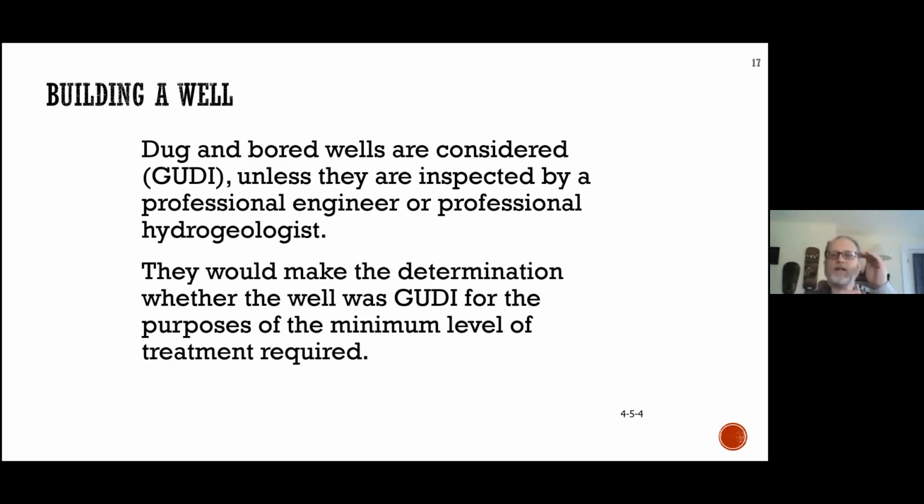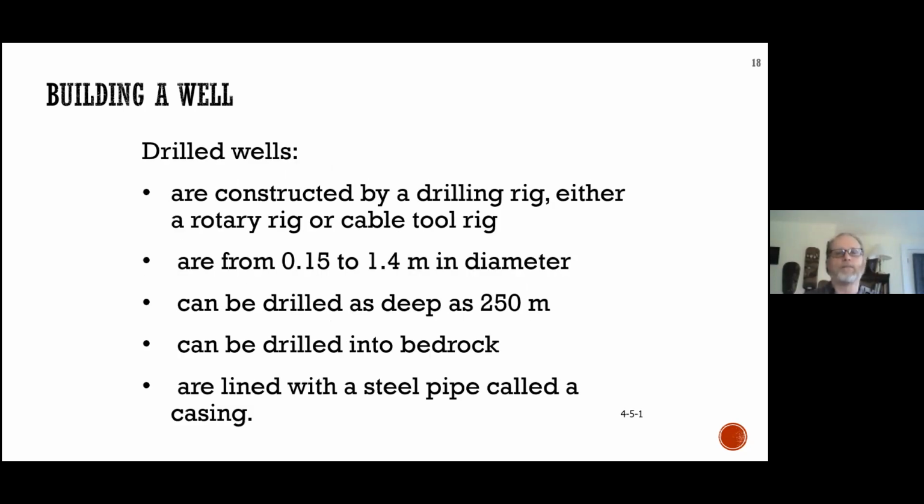And if they determine that no, even though it's a fairly shallow well, it has been installed correctly with a sanitary seal, that the surrounding geology of the aquifer is supported enough that we're not getting water down alongside the side of the casing or percolating into the ground in the vicinity of the well, then we can treat it truly as groundwater. Otherwise, that becomes the minimum requirement.